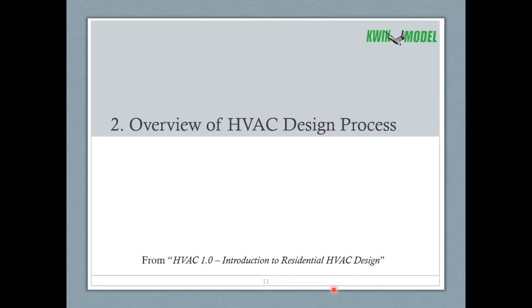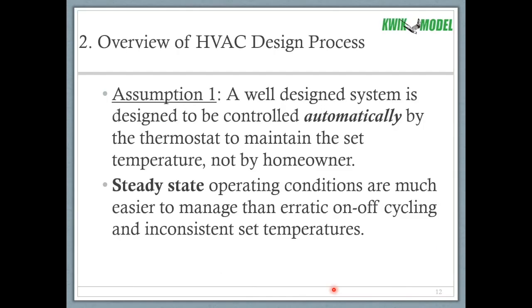So now a quick overview of the overall HVAC design process. Something you have to realize from the beginning, assumption number one: a well-designed system is designed to be controlled automatically by the thermostat to maintain a set temperature, not by the homeowner. That's very important to understand. We are designing a system to operate at steady state conditions, and what that means is things are changing very, very slowly.